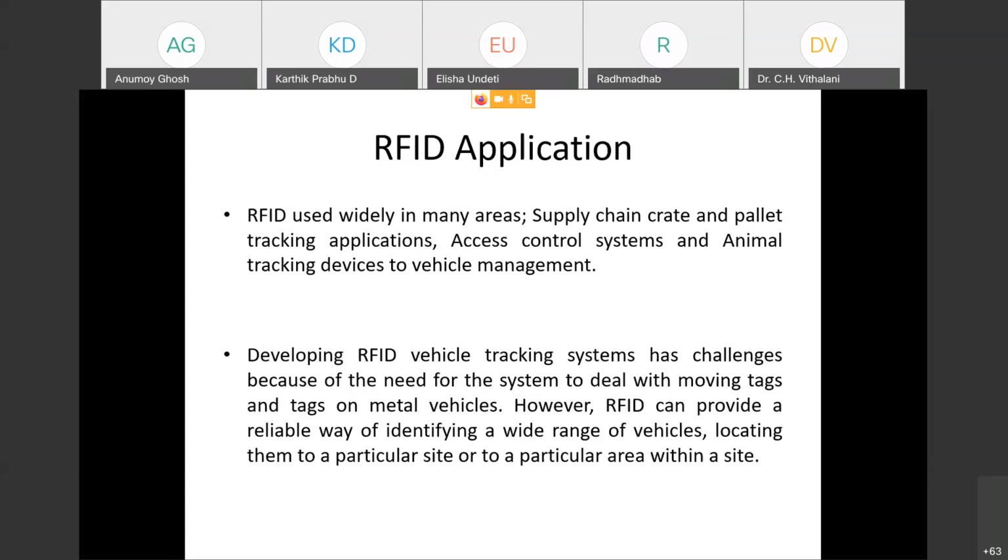But if it is a circularly polarized antenna, circularly polarized means what? It will be able to sense the electric field from any direction. Suppose the read range is 5 meters, and you take the reader to be at the center. Then from 5 meters to the left of the reader to 5 meters to the right of the reader, in this entire range when the car is moving, the reader will be able to sense the tag, because the orientation of the electric field with respect to the reader is not a matter of concern, since it is circularly polarized.